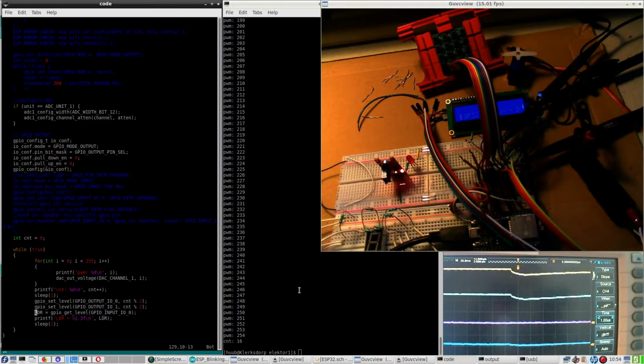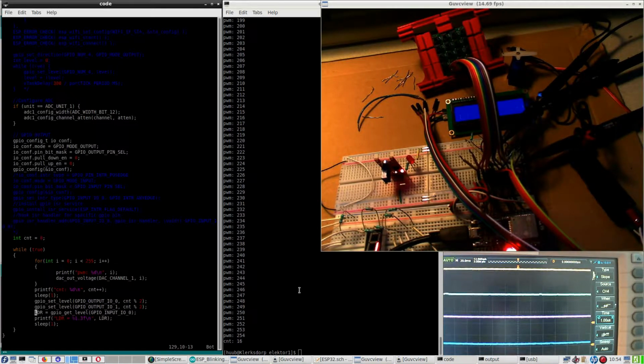So how can the LDR work nicely on a digital input only with Arduino and not with the toolchain, since that value is entirely 0? Well, because input 36 is an ADC, analog to digital converter, which apparently in the whole combination of Arduino IDE with ESP32 works flawlessly, but using the toolchain you have to set it and you have to sample it.